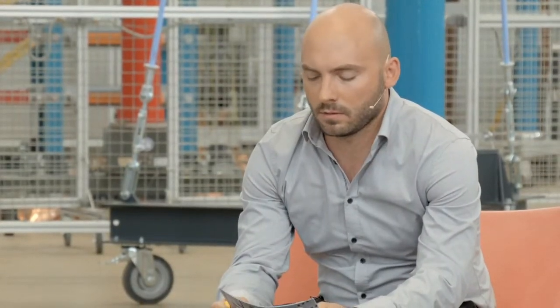What I can tell about this topic is that from the cable view, you have the so-called TDR, time domain reflectometry, which is more or less a reflection measurement to get your failure localization. And for transformers and GIS, you have the acoustic and UHF measuring technique to do a localization. But maybe, as I tried to mention a little bit before, one PD signal, if you really look at the signal, should be enough to find out where it comes from, because everything is hidden in the signal. So I believe that there will be techniques and possibilities to improve there in the future. Thank you very much, Eric, for this final statement.